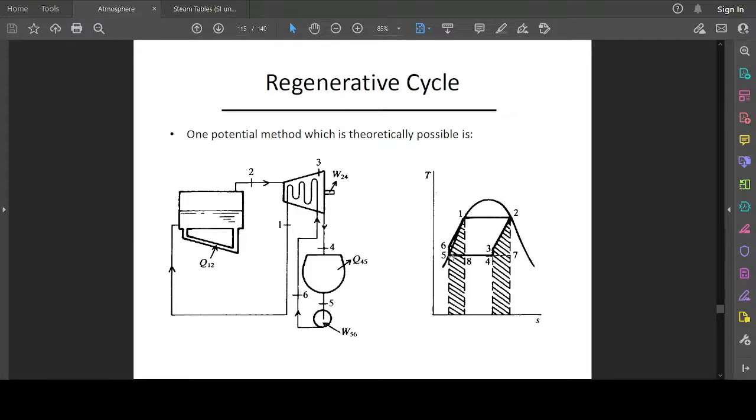And with that, you can see that from stage 5 to stage 6, the difference in temperature according to the boiling curve is not that much, and it can quickly get to the temperature required at stage 6. And also we can use it to get this temperature closer to the boiler temperature before it is isothermally heated again to saturated vapor at stage 2.